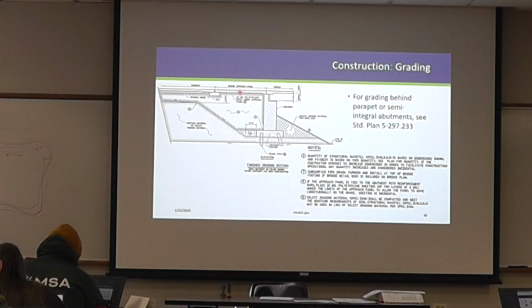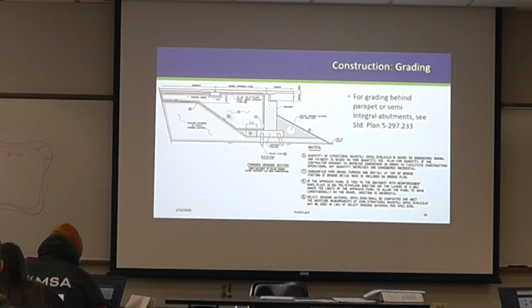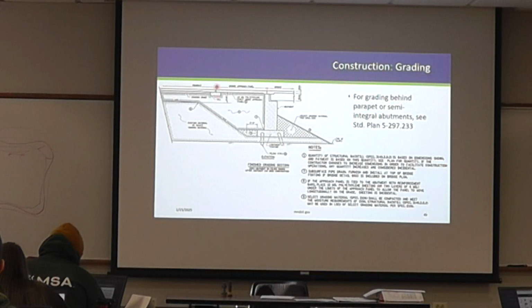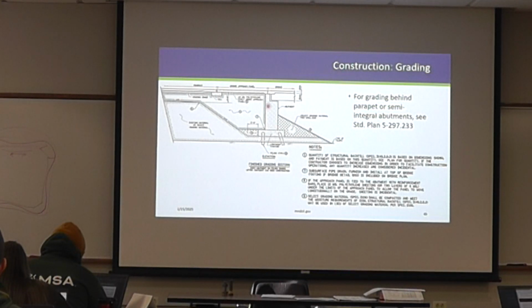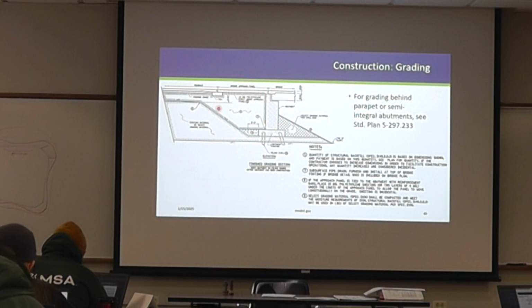This will also show the polyethylene, the sill details, etc. But really, I think getting the grading right here is pretty paramount, because if the sill starts settling a lot, that's when you start to get a less comfortable ride going over. If this is settling, and you can tell this one's on final, it's not going to settle really. So getting good material down here is pretty important.